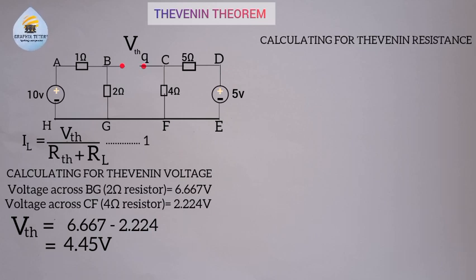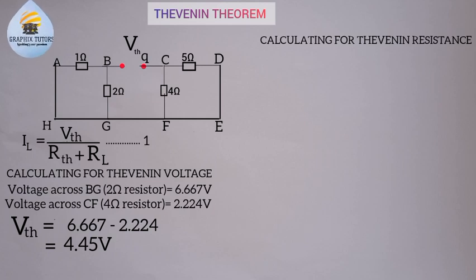Short circuit it, right? So if I short circuit it, that means I'm going to remove the 10 ohms, the 10 volts and the 5 volt, and I replace the wire. So this is what I'm going to be having, right? And don't forget, you also remove your 3 ohm resistor that you're considering, and you write your RTH instead of you put your VTH here. So you remove the VTH, you replace with RTH, and you remove the voltage source.